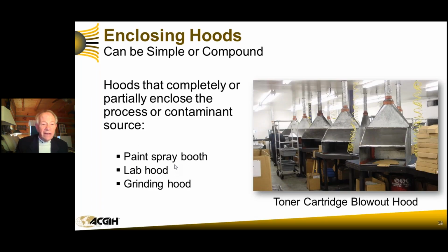Laboratory exhaust hood. That is probably the second most successful hood of all time. And then a grinding hood, which is also probably the third most frequently found hood available anywhere. So when you enclose your process, and this is something we say in toxic materials, we say that you should never use an exterior hood or a capture hood with a toxic unless you have to, because when you can completely enclose the contaminant, you will be successful every time.